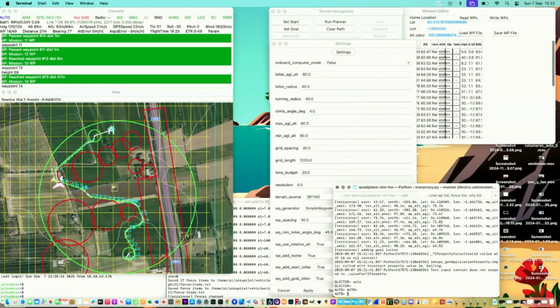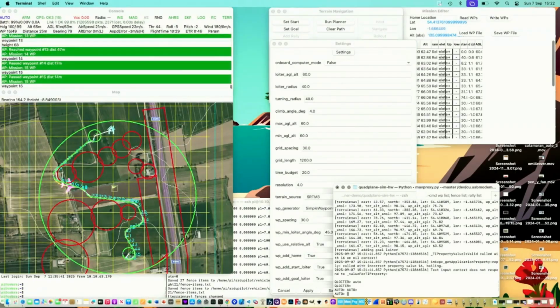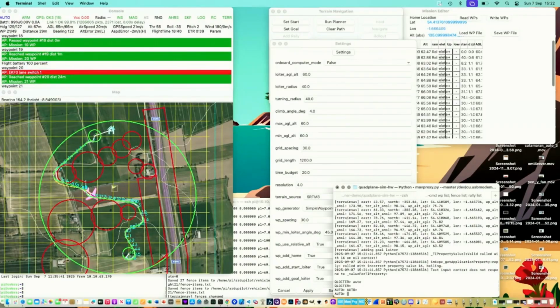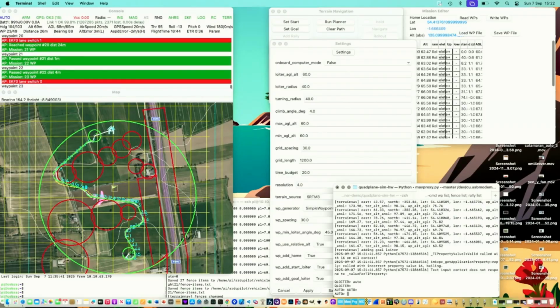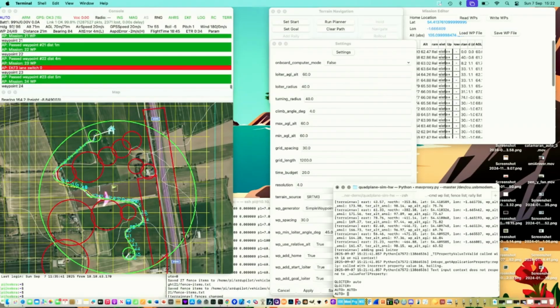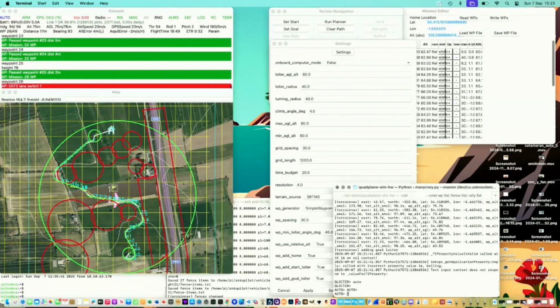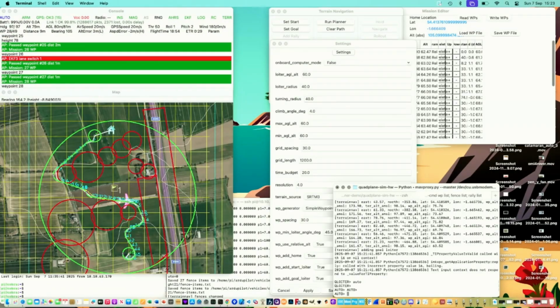And the idea this morning was just to have this working, which it was, and then basically drop the Pi into the plane and just swap the plugs over. But unfortunately, the board has had a change of pinouts on the way through. We managed to choose the one UART which had been moved out of all the other free ones, which is a bit unfortunate. So as we move, I'm going to wait, because it's SITL on hardware, I don't think the speed up works. Are we out of time? Pretty much, yeah. Yeah, okay.